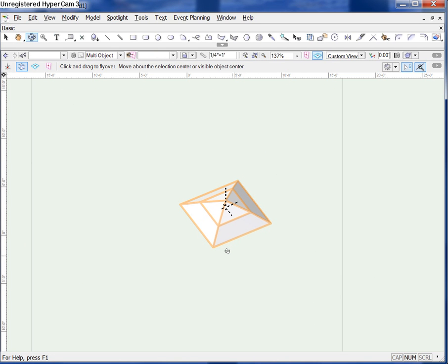Now if I wanted to create the Washington Monument, kind of an obelisk thing, I would have to do that with a loft shape because I'd need to be able to control the spacing between these vertices. There's really no way for me to grab one of these vertices and move it separately, but you can do that in 3D with the loft surfaces. But again, you're not really limited to just one set of extrusions. You can do multiple steps with this tool as well.